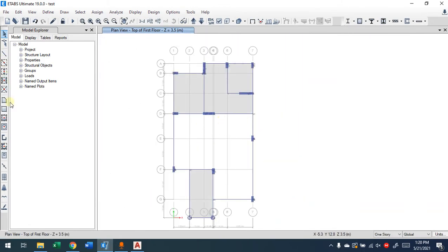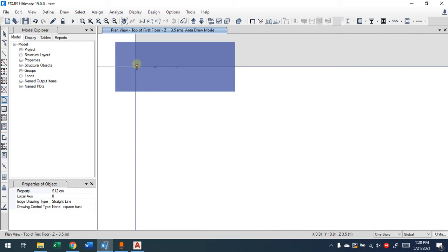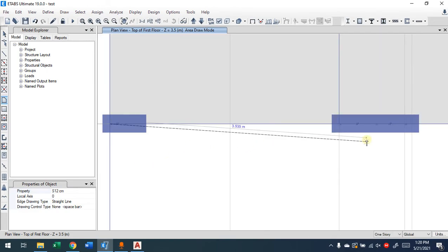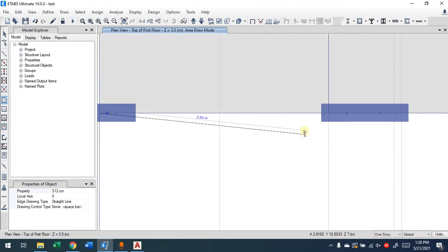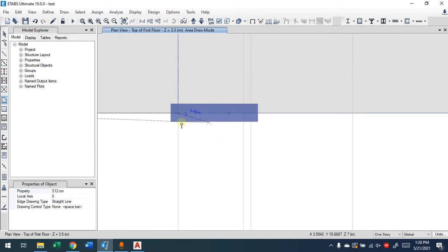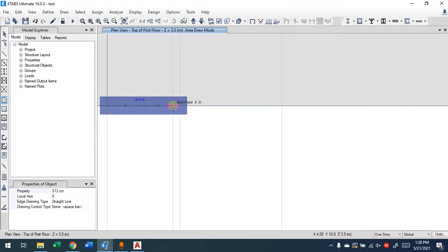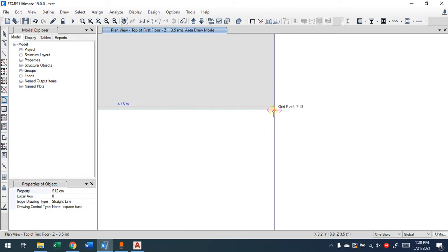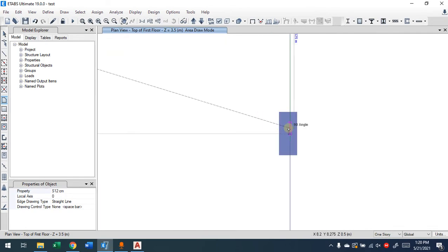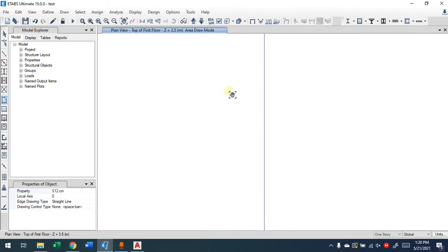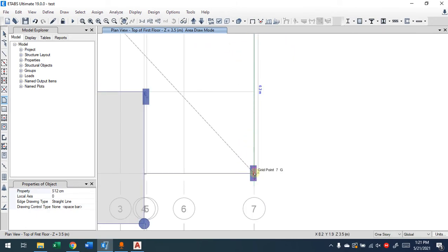Oh, we have it here. But let me just do it and show it to you in 3D. Let me go for this one fully here. By the way, when you start with a big slab, I recommend you give some joints to the slab. They say that for the distribution of the load, it will be better to have some joints along the way. For example, like this, I can even do one joint here. Here I can do it till the end, but it's recommended to have a joint to say there is a part of it here.